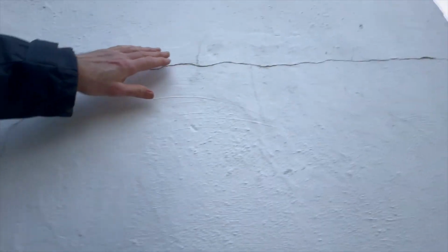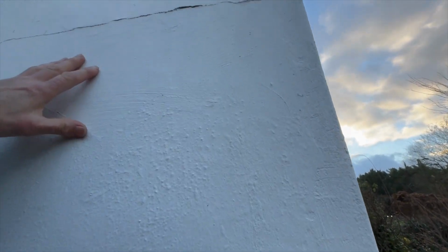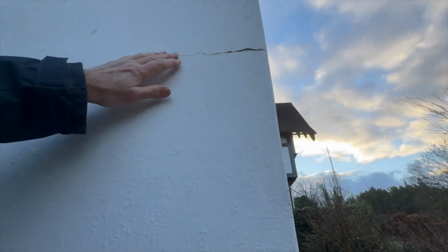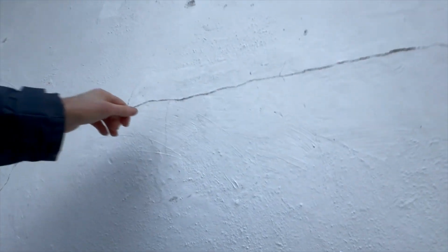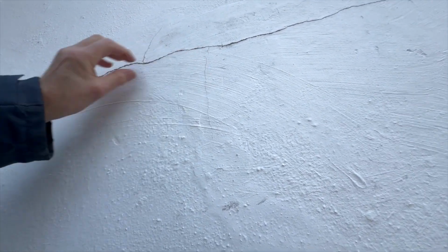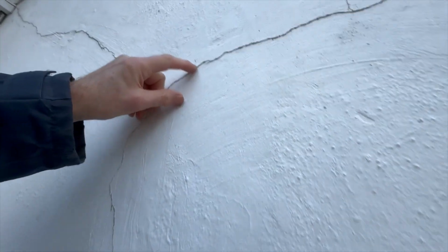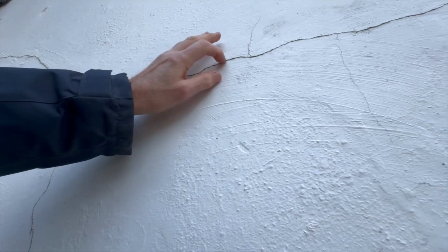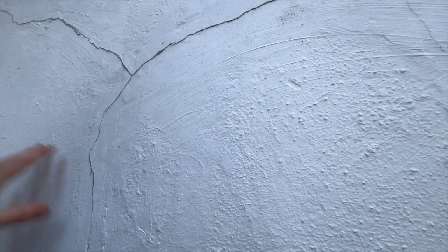So we're on the outside. We're looking at, so these render cracks can cause water to pass through into the cavity. It's difficult to tell whether it's getting through. They look very fine, but the thing is, a thin crack can draw in a lot of water through capillary action, and you can see that there is moss growing on it, so it's clearly some water in there. But if not, what it can do is just dampen the outside brick.